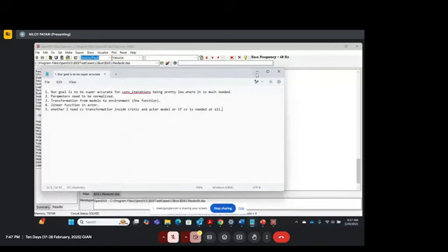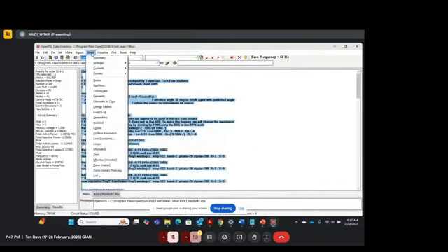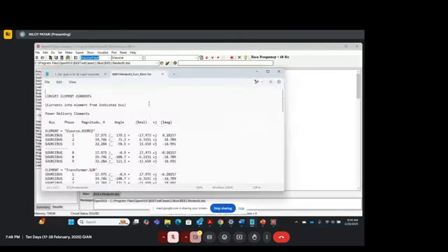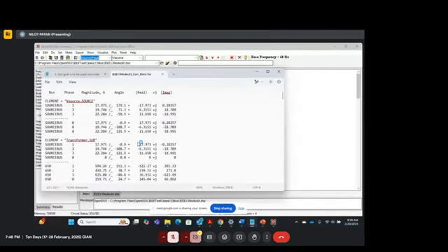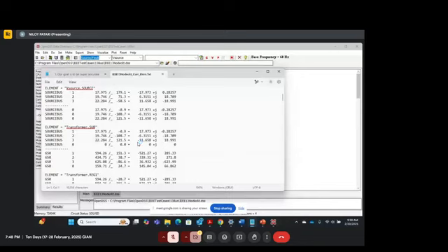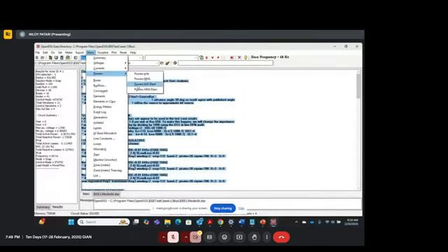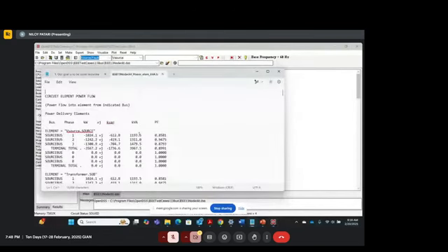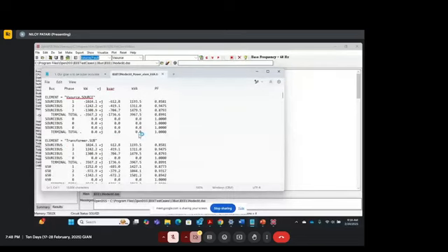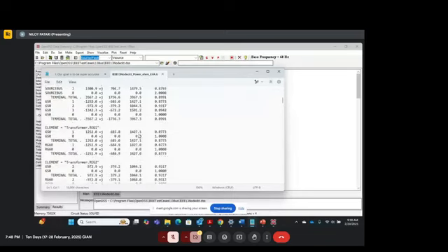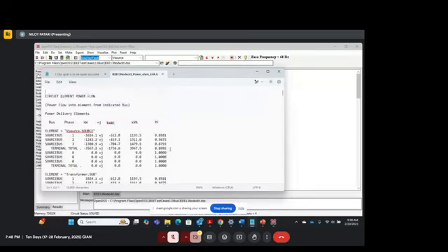what else can you see? If you go to the show button again, then you can go into powers, you can go to currents. If you go to currents elements, it will show how much current is flowing in each of the lines or each of the elements. Then you can also show powers. In powers, it will show kVA elements, so it will show how power is flowing through each of the elements, right? And it also shows power factor on the right hand side.